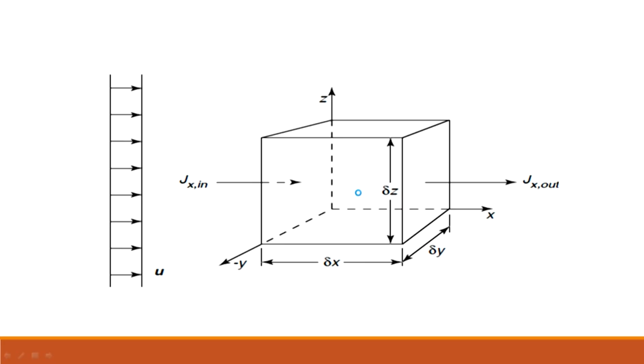So, again, how do I predict this or how do I understand this now, right? It is not a bigger model, it is a smaller model that I need to look at. So, I need to know the mass flux. Flux with respect to mass here is mass per area per time, right. Flux coming in, mass flux going out of that particular compound. So, that is why we need to choose a compound upon which we are applying the mass balance. And also I need to understand or frame my control volume, let us see, right. This is my control volume out here, and then any reactions occurring within this particular control volume, right.